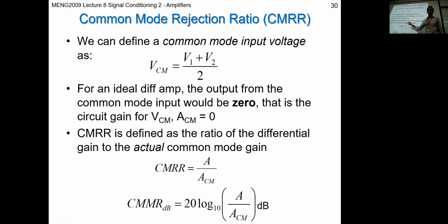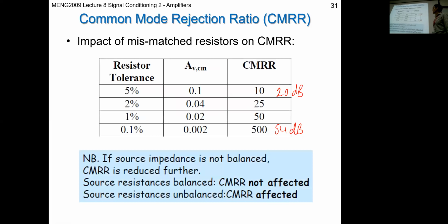The reality was, the other column had about 120 decibels, right? So that would have come from this calculation here. What's the amplification or the gain of that amplifier versus the common mode gain from the same amplifier? And typically our common mode rejection ratio is in this range of decibels, 60 to 110.